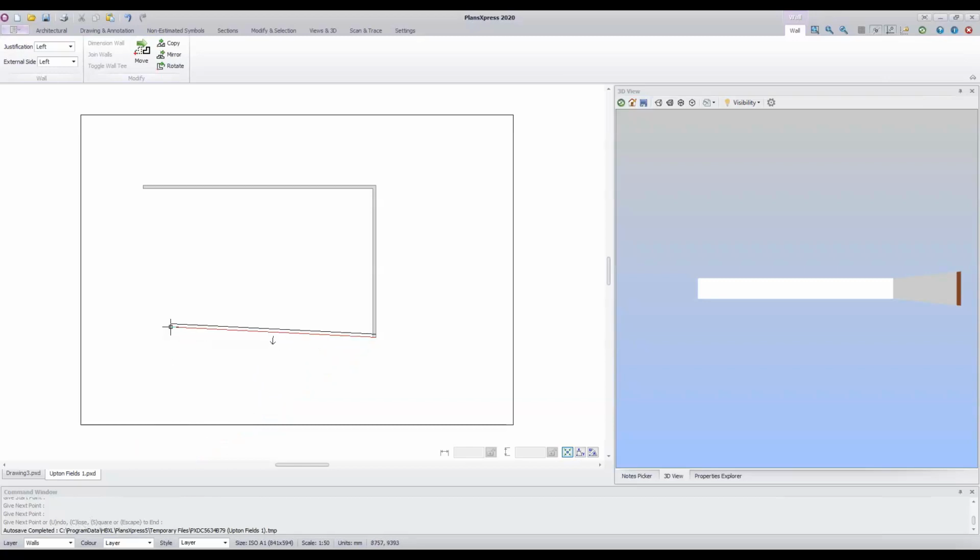What I'd like to do is show you how you can use an endpoint on another point on the drawing as a reference, basically, for placing a point on your walls. If you hover your cursor over the endpoint where we started drawing our walls, you'll see that snap point after a moment turns pink. It starts off blue and then it turns pink.